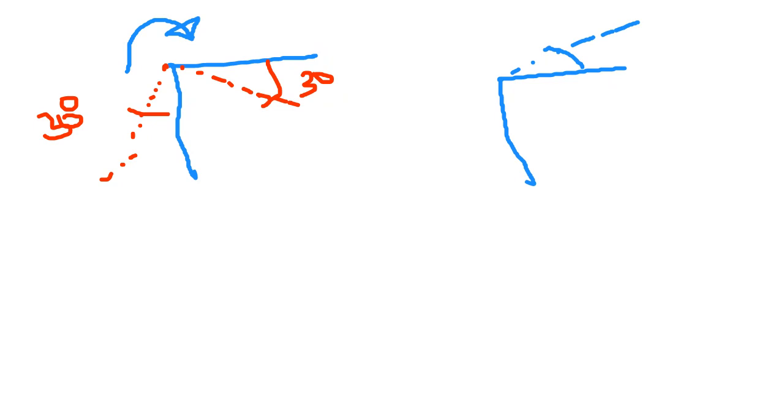This may remain the same, because the hinge is trying to restrain it, but the rotation will not be transferred to the other member. Maybe it will slightly rotate that member because of the joint, but it will only restrict this point in terms of not moving on this side, not going up, but it will not restrain the rotation.